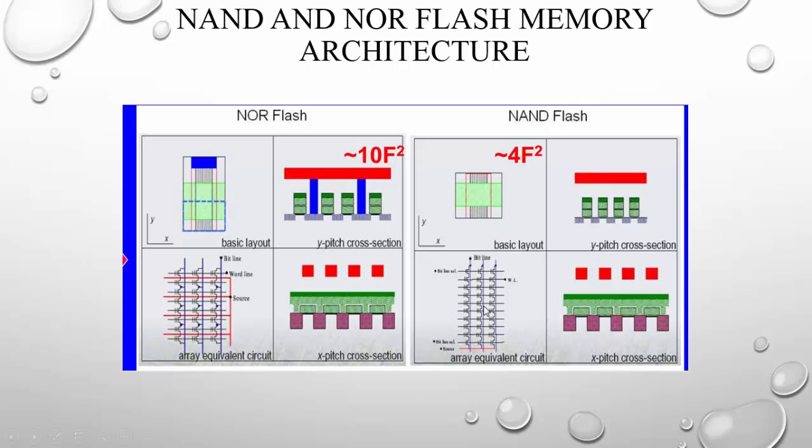If you connect 8 memory transistors in series, that is basically NAND flash technology. Utilizing the NAND flash architecture, with high storage density and smaller cell size, NAND flash systems enable faster write and erase by programming blocks of data. So NAND flash is ideal for low cost, high density, high speed program erase applications, often referred to as data storage applications.